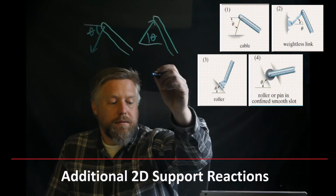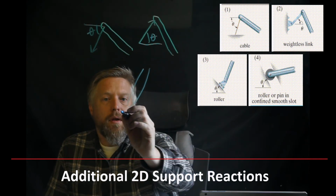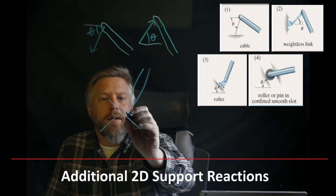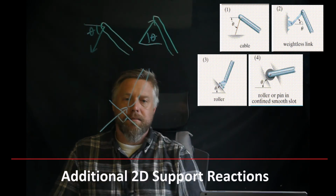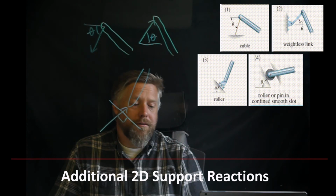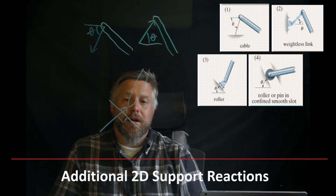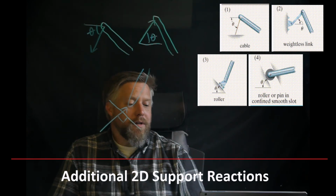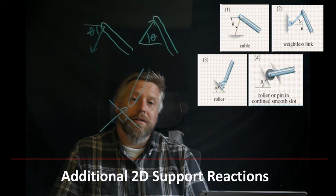Well, just like we did with the previous one, we'll take away the support and we're going to give it a single force that's perpendicular to the surface that it's acting on, because that surface can only push back perpendicular to itself. And we're going to have one unknown because the surface is going to tell us what direction that force is in. Very similar to the one next to it, like a bearing inside a sleeve.